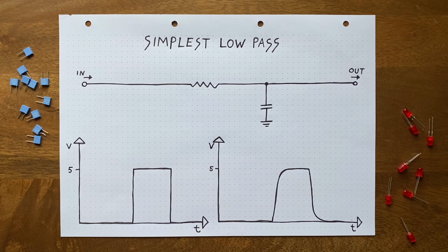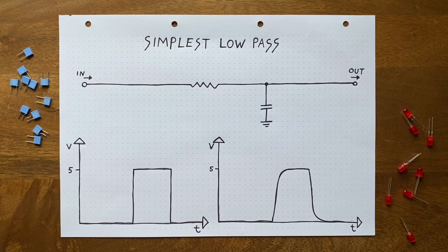If you want to build along, make sure that you use either a foil or ceramic capacitor, anything that isn't polarized. And that's because, unlike with our example, audio signals mostly swing across, not strictly above the 0 volts line. While this has no general impact on our filter's functionality, it would pose a problem if the capacitor was polarized, because polarized capacitors really don't like negative voltages.